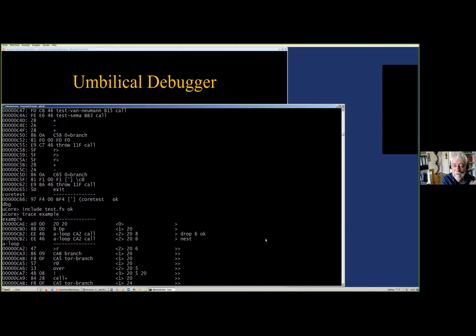So there's a new parameter that tells you how many byte address bits are in an address, and if you have a 32-bit system, you have to set it to 2, because 2 bits for byte addressing, and then you have real byte addressing. If you don't want byte addressing at all, you just set the byte address width to 0, and then microCore works as before.